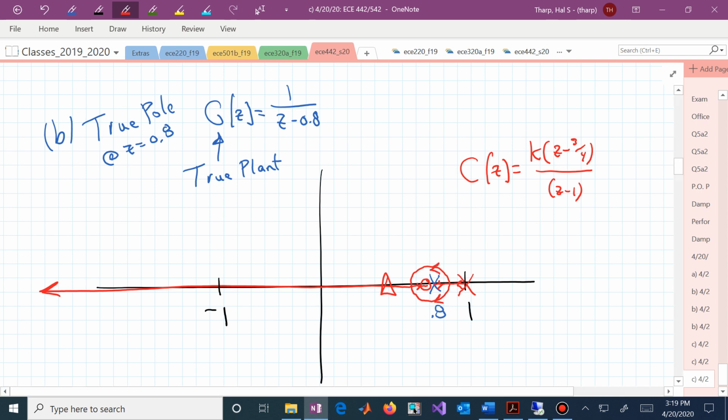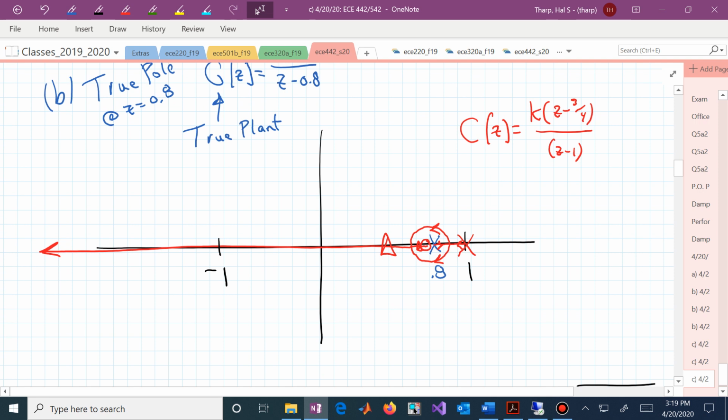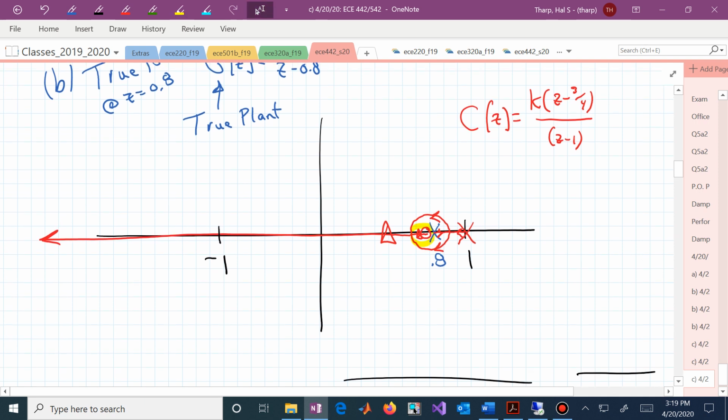In order for these 2 branches, one to already be going to the left, the other one now has to be going to the right, and it's now getting close to or nearly on top of that 0 that we had established before at 0.34. So that now we have again this near pole-zero cancellation, and the deltas correspond to our closed loop poles.